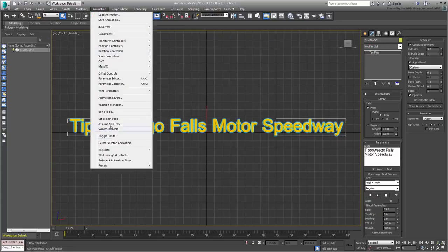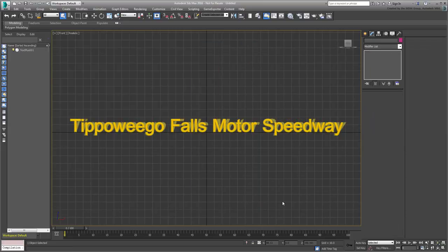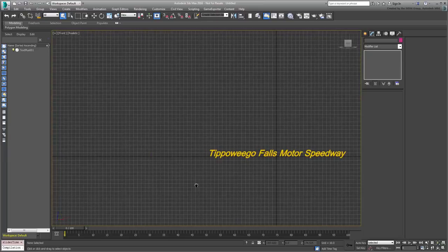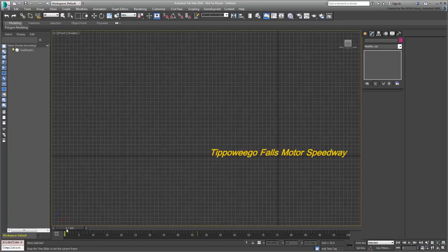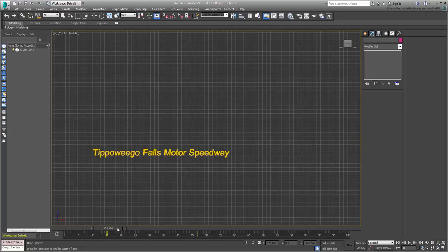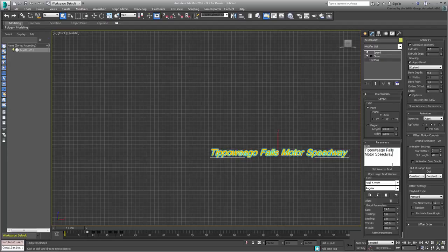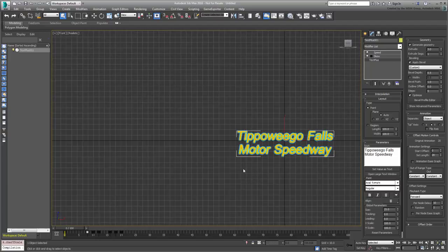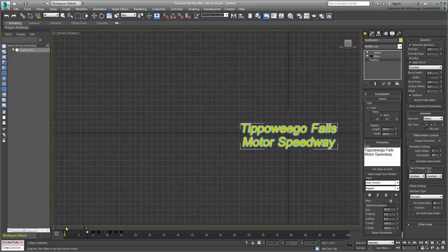Load onto the text the animation preset named Speed that you downloaded for this tutorial. It is based on a simple X position transform and a skew modifier simulating a hard brake. If you want this logo to spread over 2 lines, you have a couple of choices. One way would be to simply edit the body of text and use the Enter key at the right spot. This, however, creates a paragraph break that can be significant when the animation is applied. Back to that in a moment.